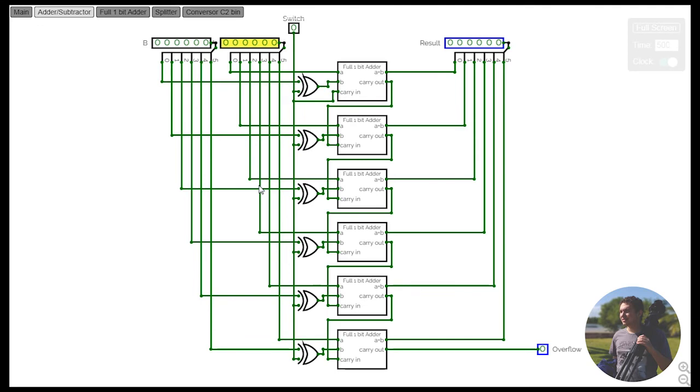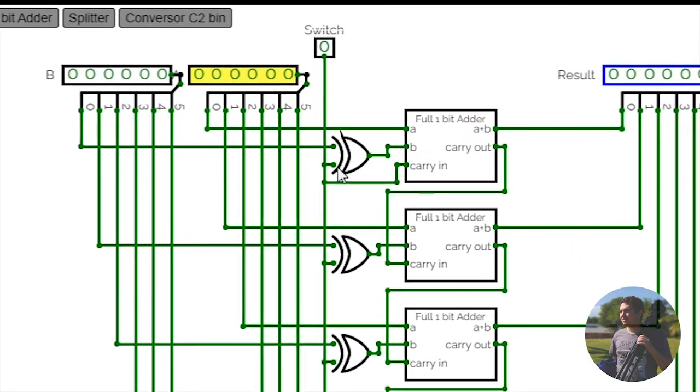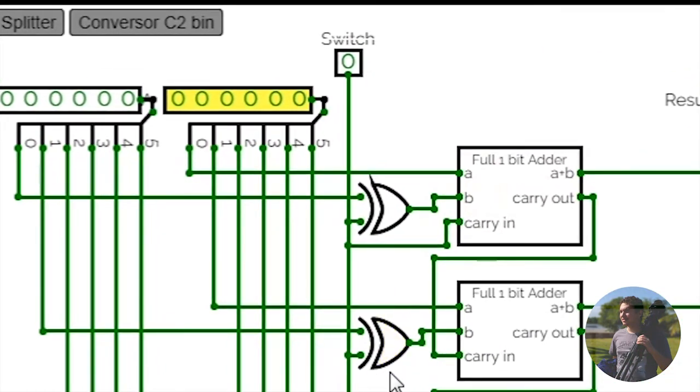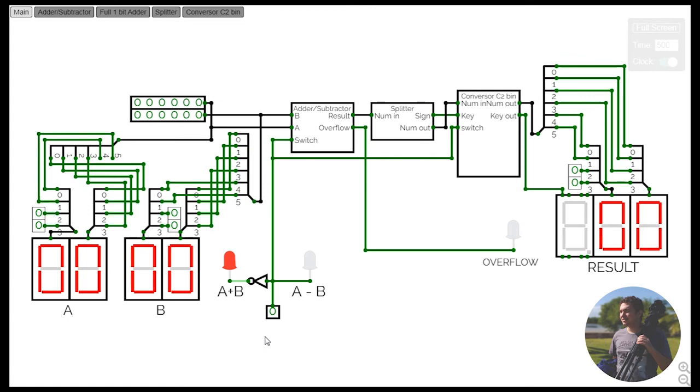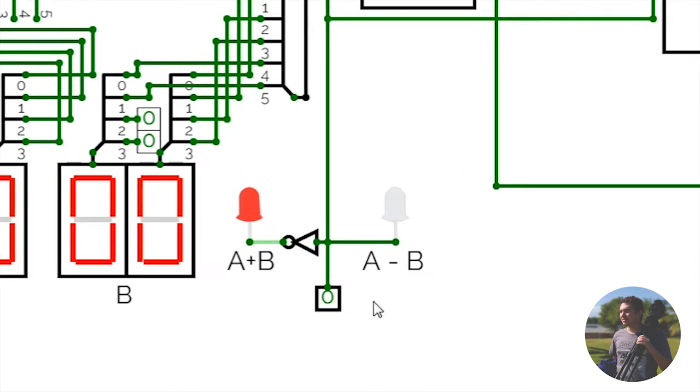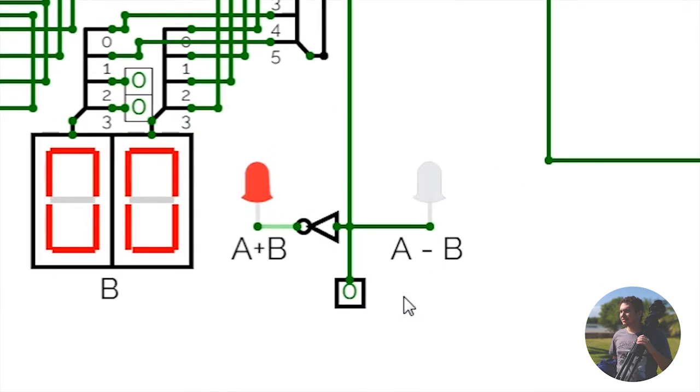Now, the same circuit is also capable of doing subtraction, utilizing 2's complement. It does that through these XOR gates, laid out before each B entry, in the adders. All these XOR gates are connected to a key bit. Yes, this is the same bit used in our key which allows us to switch operations. Let us remind ourselves. On the 0 position, the calculator performs addition. On the 1 position, it performs subtraction.